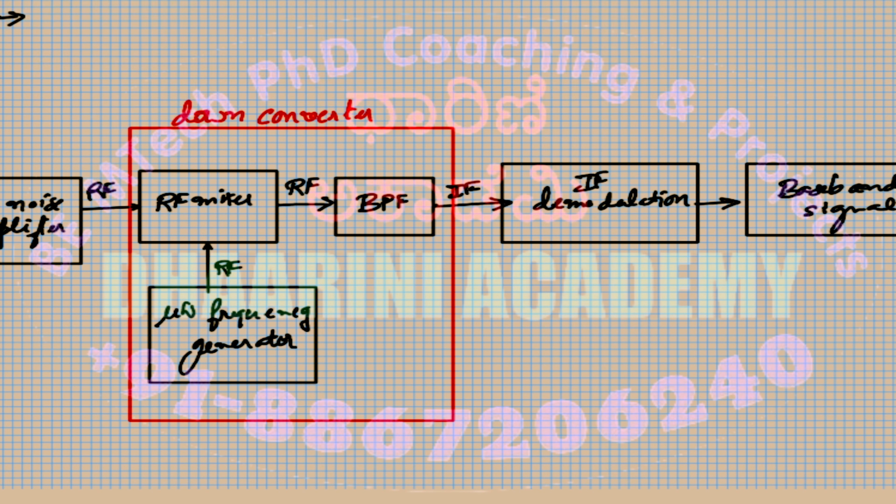Starting from the conversion of the baseband signal into an RF frequency in the uplink station, and converting from the uplink signal to a different frequency for the downlink signal in the transponder, and then receiving the downlink signal and converting it back to the original message format, right? These three parts together build what is called a space communication network.